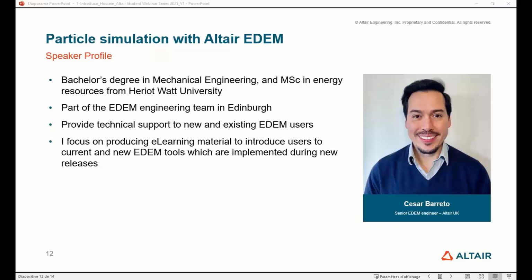One question from my side. Is there a limitation with the number of particles that we simulate in EDEM? This is a very interesting question, and also very common. Many people, when they start using the software, want to know what their limitations are, and the answer is there is no limit on the number of particles. However, you need to find a balance between how long you want to run your simulation and the accuracy of the results.